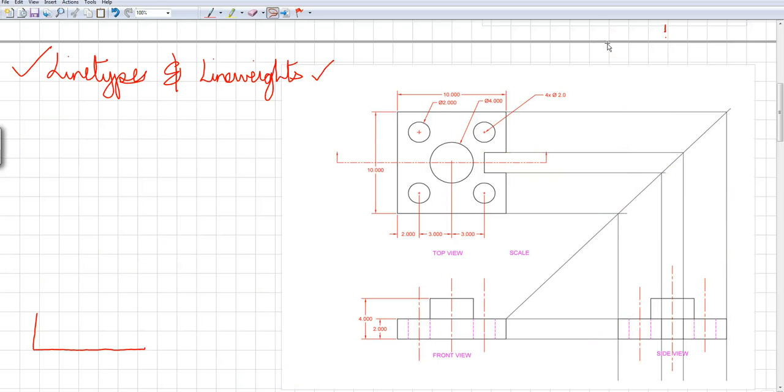Now what are line weights? Line weights are just lines that are drawn in different thicknesses. Like you have a pencil grade H, then you have B, then you have 2H, then 3H, right? The lead keeps going thicker. So why would we do that? Again, the reason why we would use different line weights in our architecture drawing mostly is when something is further away in the drawing, then I would draw it at a thinner line weight.